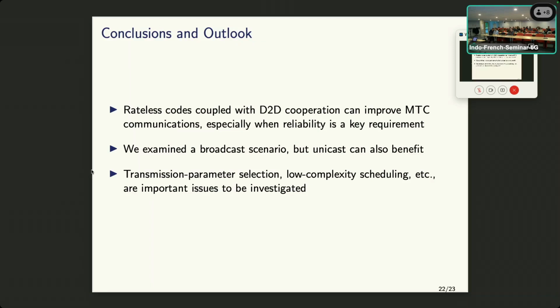In addition, if needed, we can divide the overall firmware update into smaller blocks. Rather than running the fountain code over 200 blocks, maybe we can divide them into smaller blocks of size 40, and then run it. That way, we might be able to reduce some complexity.